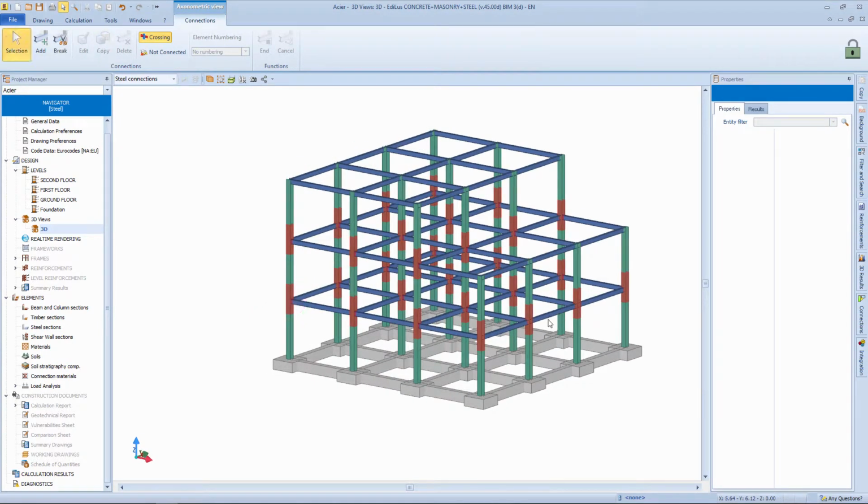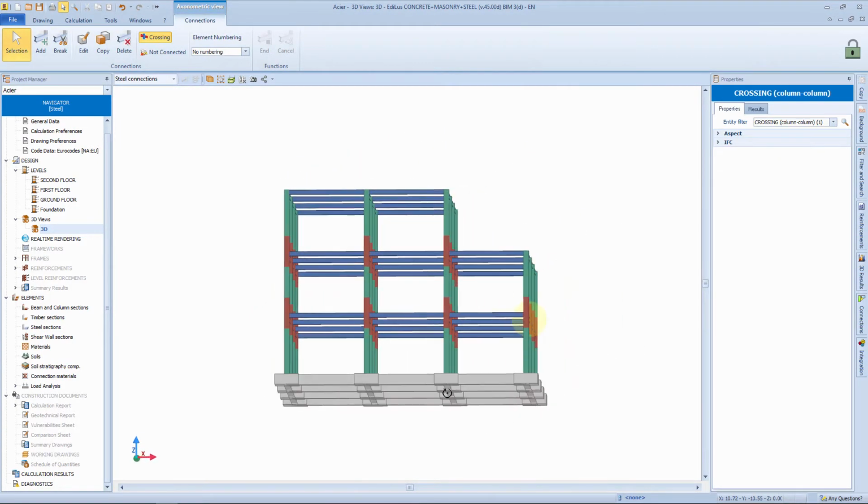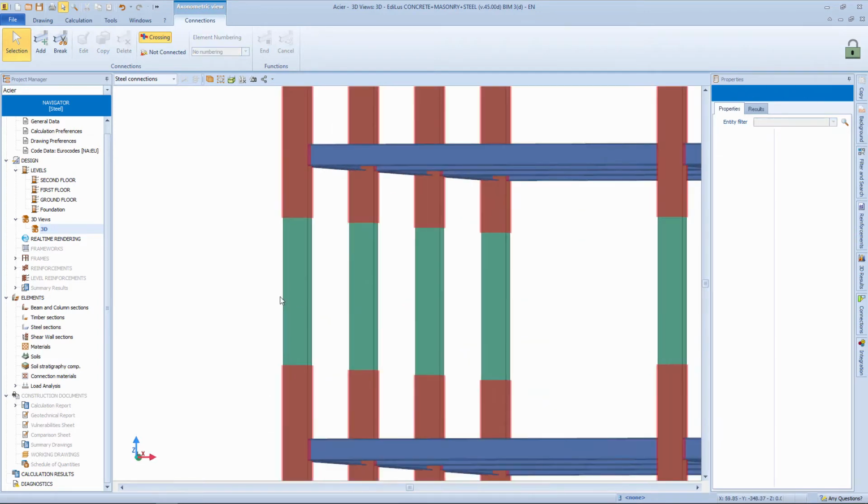But the steel columns have predefined dimensions, so at some point it will also be necessary to insert an interruption. To do this, there is the break command, so let's apply this function on this column. Also define a precise dimension by inserting the numerical value. Then, with the copy function, let's break all the other columns of this model.